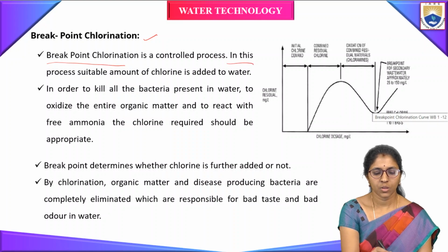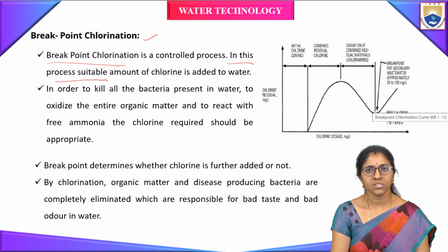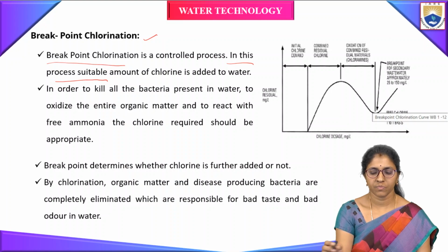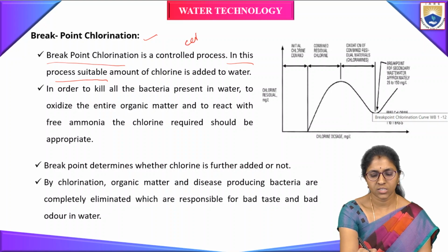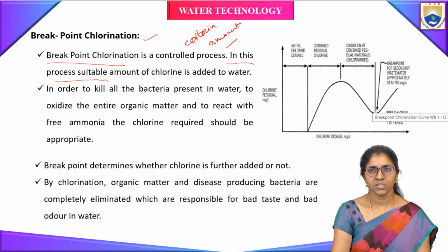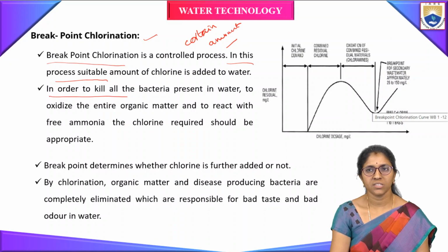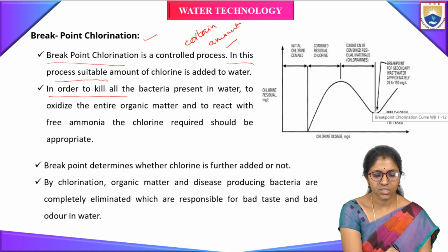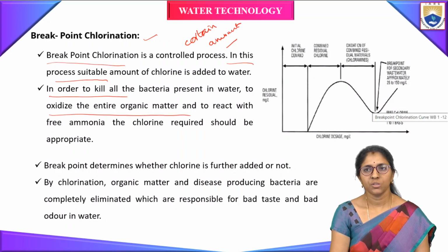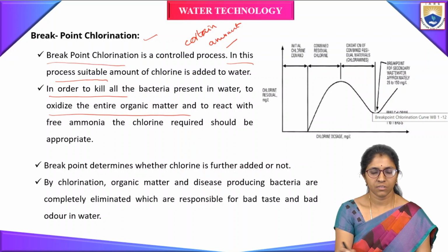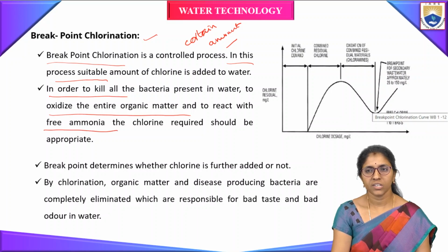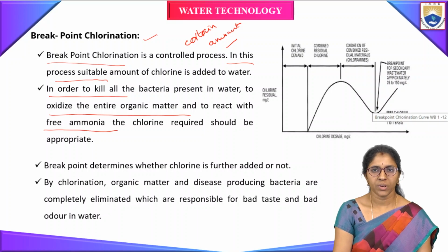In this process, a suitable amount of chlorine is added. A certain amount of chlorine, suitable for the water we are taking. In order to kill all the bacteria present in the water, to oxidize the entire organic matter, and to react with free ammonia, the chlorine required should be appropriate.